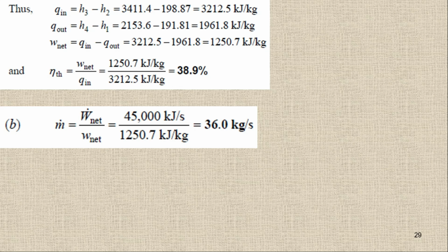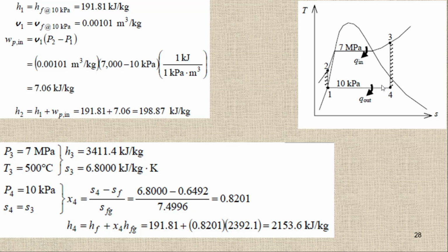Now the mass flow rate is already given for the cooling water, and you have to find the temperature rise. So here in the condenser, what happens? This is the condenser. We have the tubes around this condenser, and this is basically a heat exchanger. The heat from the condenser will be absorbed by the water circulating around it. So the Q out from the condenser will be equal to the Q into the tubes of the cooling water. The amount of heat rejected by this condenser will be the heat gained by the cooling water.